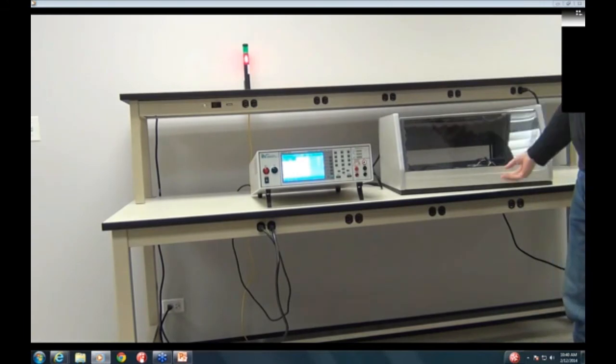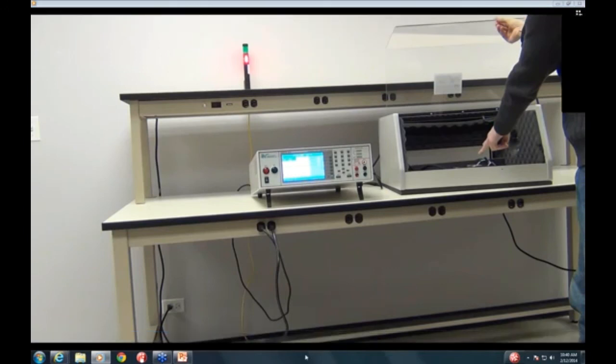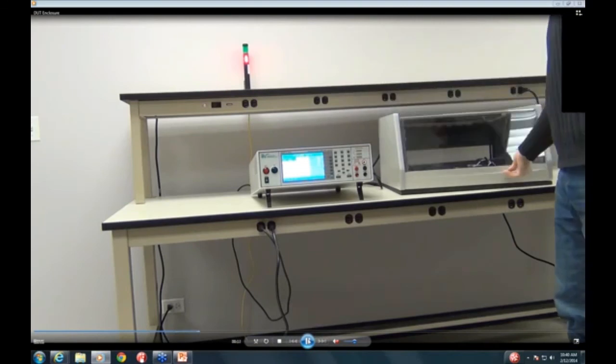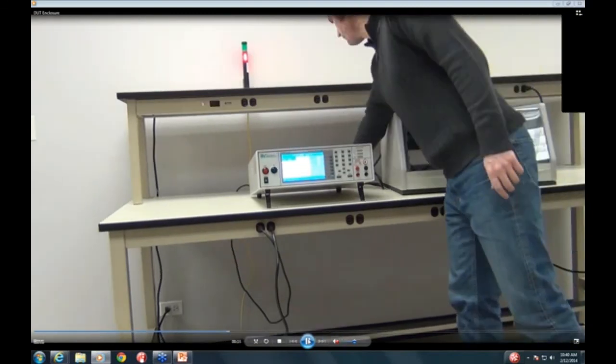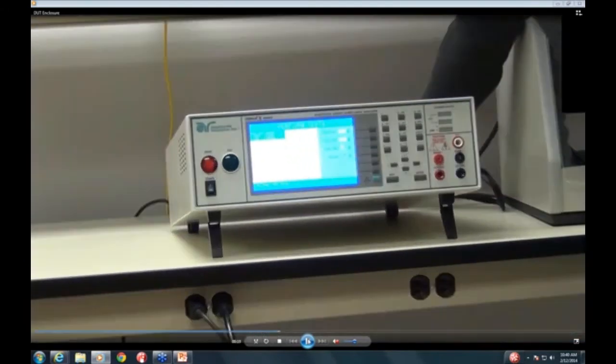This is my DUT enclosure. As you can see, I have the door open, and I have my testing product in the enclosure. I'm not going to show you connections or anything. We're going to save that for the next webinar. The important thing is I have my DUT hooked up inside the enclosure. So I'm going to shut the door, which is wired directly to my interlock on the back of the HiPot. I have those doors wired with a magnetic switch across pins 4 and 5 on my HiPot unit, and that ensures that if that door opens, the unit's going to not output voltage.